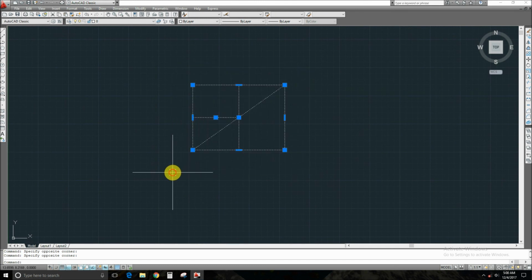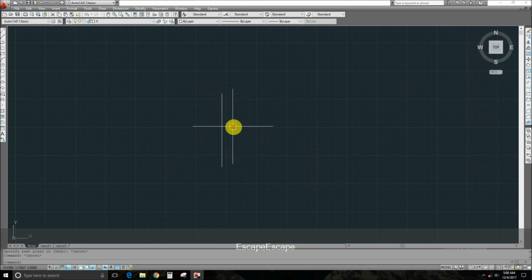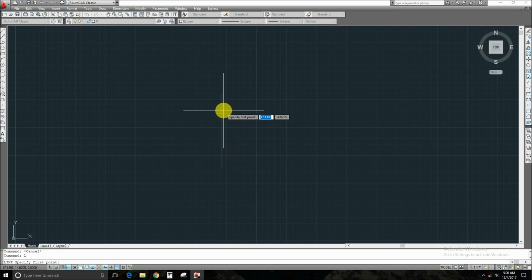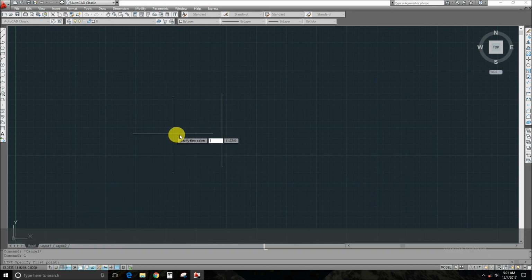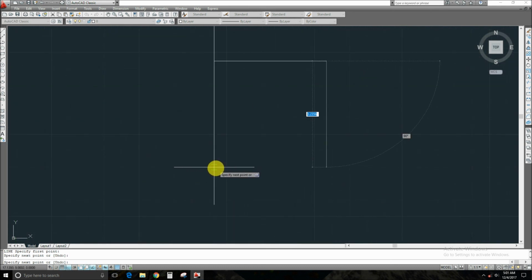So I have shown you how to work on object snapping and grid snapping, and now let me show you how to work on object snap tracking. This will help in making a line. If I'm making a line here, and I'm not having midpoint snapping, let me turn this on. By here you can see, if I want to make a line here and I want a reference, take a look: these reference lines will guide you how to make a line on this path.